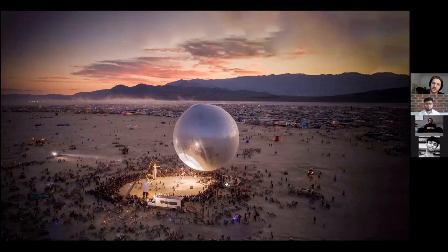So the main challenge of this was, how do you keep a thing like that from blowing away? And how do you keep it in a shape like this? So what we did was we modeled this, but not just as a sphere on a stick. We used a tool called Kangaroo and K2 Engineering, where we could actually simulate the physics of this structure. So we modeled a membrane, we blew air into it, like this is an inflated ball basically. So our 3D model was an inflated ball.